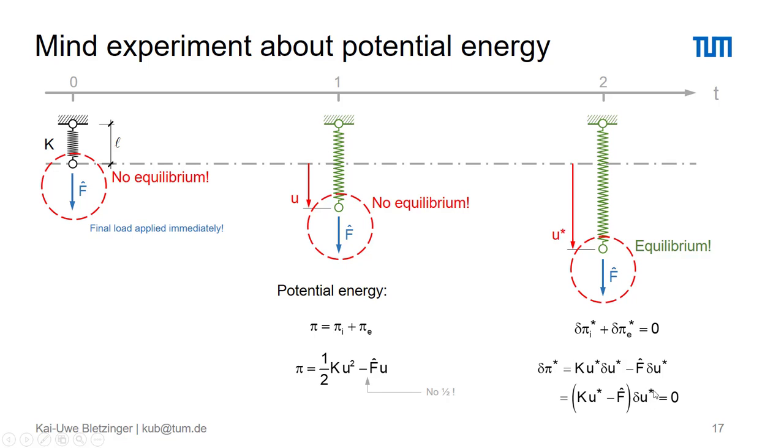You can choose what you like here, any number. The variation of the energy is always 0. I'm almost sure that is known to many of you, and we will make use of that later, to take the variation of the displacement completely arbitrary and concentrate on the rest, typically the equilibrium equations.